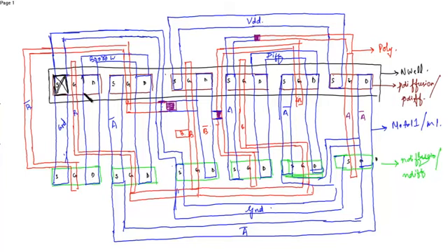Similarly over here, you can see there are 6 PMOS, 1, 2, 3, 6 PMOS, and each has a source and a drain connected. So total 6 into 2, 12 contacts. So here you have to place the contacts.